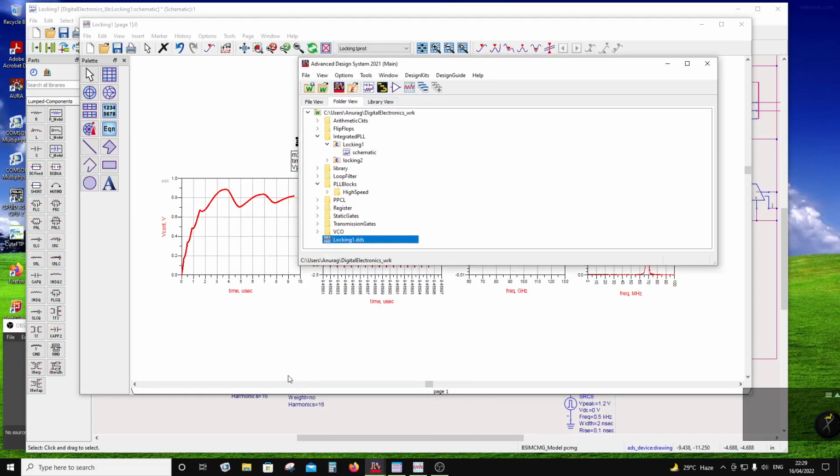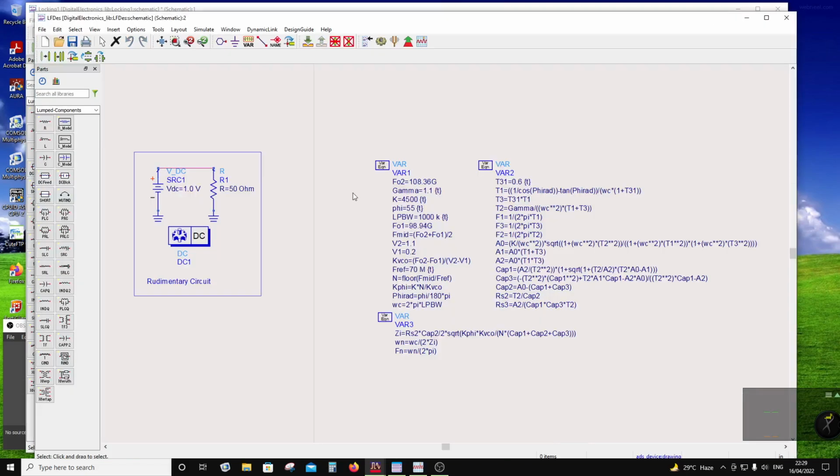In this project, let's look at the loop filter design. I automated that. I have written a bunch of equations for pole placements, and then I choose a loop gain, a loop bandwidth, a given phase margin, and the extent of frequencies. Based on that I calculate KVCO, and then I find the total loop gain, K phi times KVCO by N.